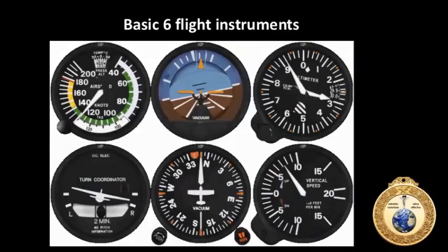So here's a little zoom in, a face-to-face view with these instruments. Our airspeed indicator tells us how fast we're going. This aircraft is moving about 130 knots, just a hair off. We're in a right turn, not really climbing, maybe a little bit, but we're definitely in a right turn, a little bit past 10 degrees.